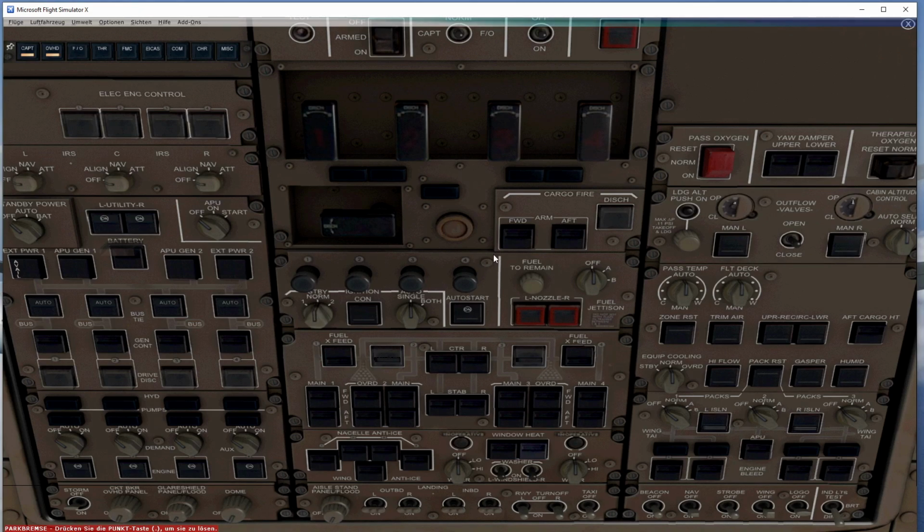Right next to it you have the engine start panel with the 4 engine start switches, the ignition, continuous ignition. You simply need it only during precipitation, and in normal ops you hardly ever use that switch. Single or both for the ignition, and you have 2 different ignition systems. The auto start switch needs to be on, so that the airplane does the engine start pretty much automatically, or even recognizes some engine start malfunctions. So as long as the start switch is on, you don't need to do a lot.